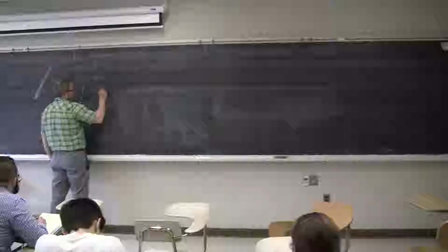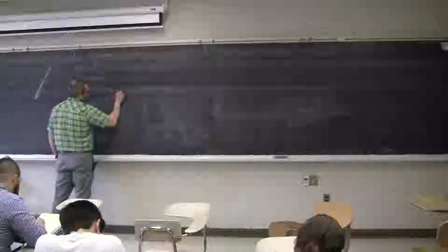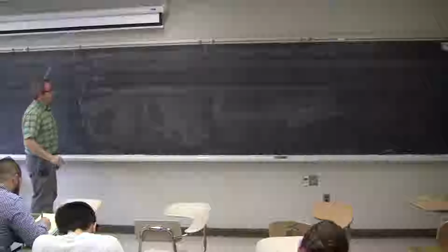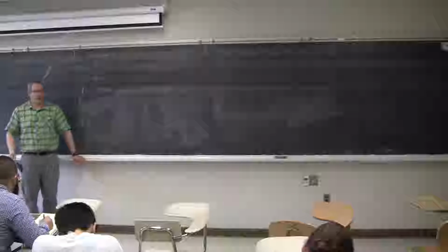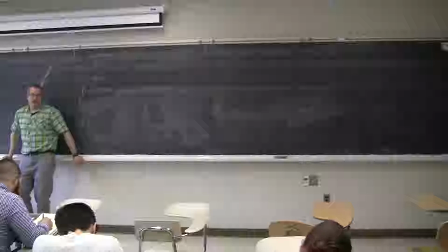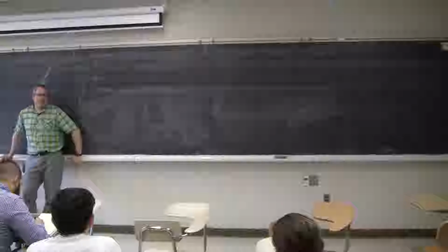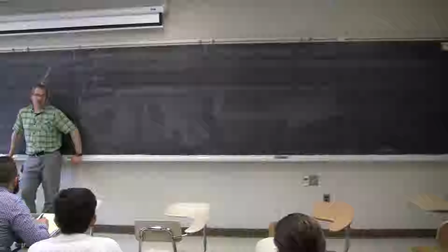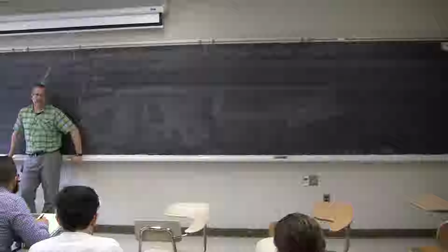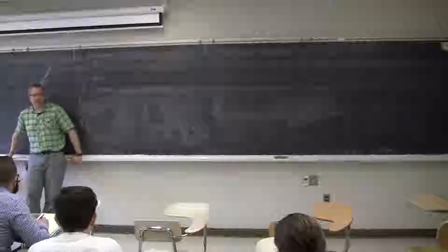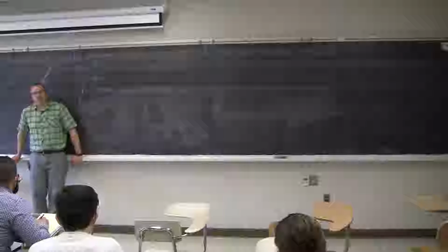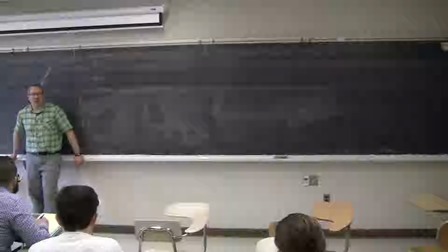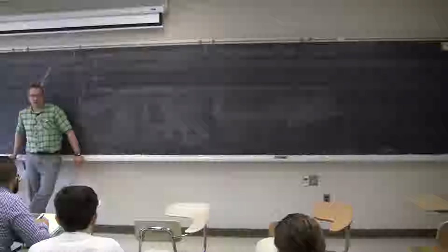Chapter 4 was, I'll just call it synchronous machines. So we started introducing the concept of a rotating MMF, right? So if we have a 3-phase set of currents flowing through a set of windings, we would get a constantly rotating magnetic field whose magnitude was 1.5 times any individual magnetic field strength.